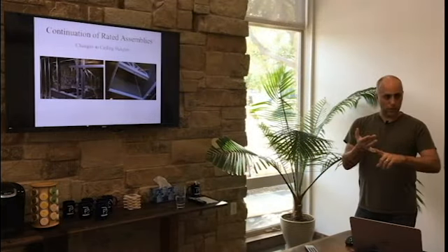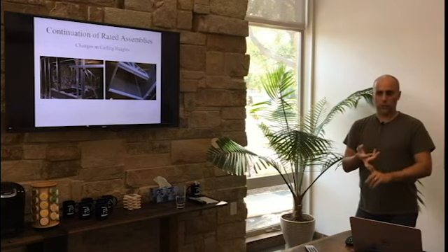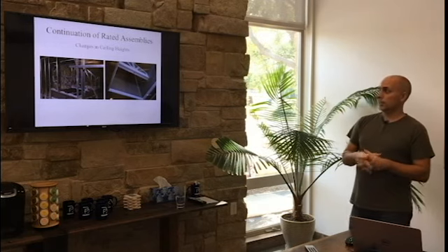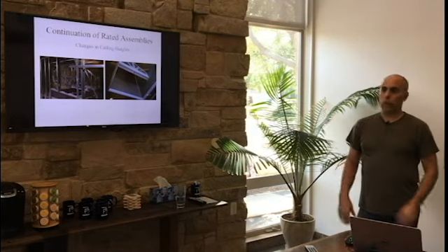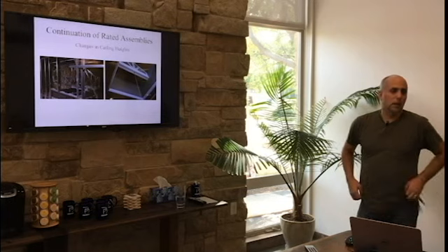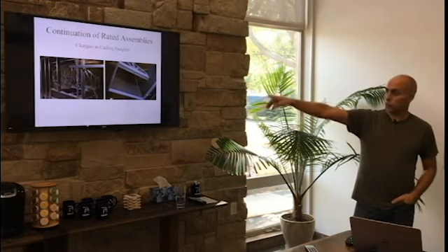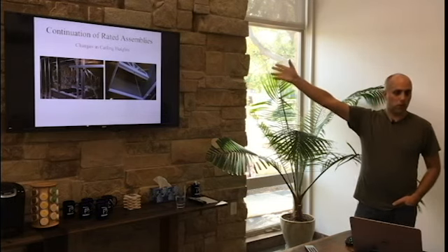Well, they needed the channels, the correct gypsum board, etc. In this particular case, they ended up having to come back and treat it as bearing walls. And it took a lot of work to get that thing to be 1 hour rated, because it's still protection of the roof structure, even though it looks like they're walls, but they're not.